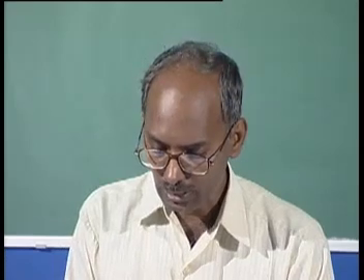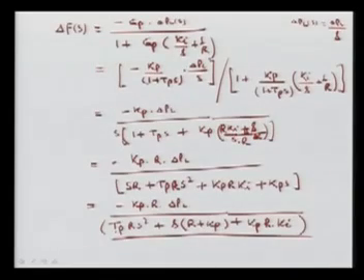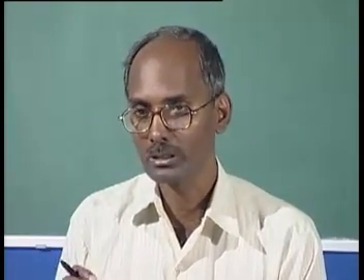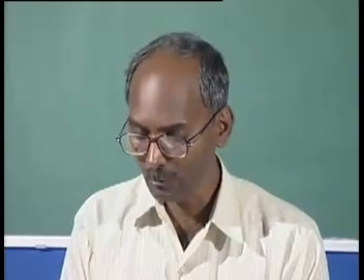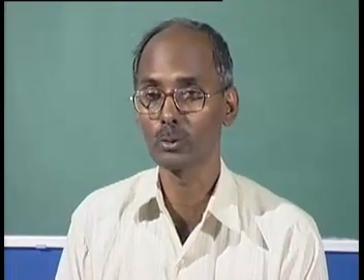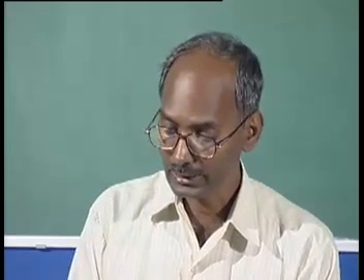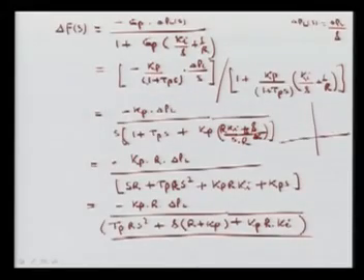To see this, here all the coefficients are positive. Here the Tp is positive, R is positive, Kp is positive, means all the constants are positive. So this gives one criteria, means the possibility of the stability is very large. If any one now is negative, then it will be unstable. One root will be lying on the right hand side of the S plane, and that is not required. Again, in the S plane, this is your left hand side. So all these roots must be on this side, and this is called the right hand side. We don't want the unstable side, here is the stable side.